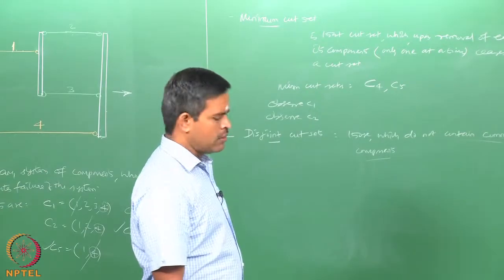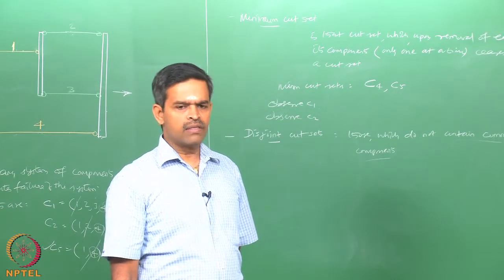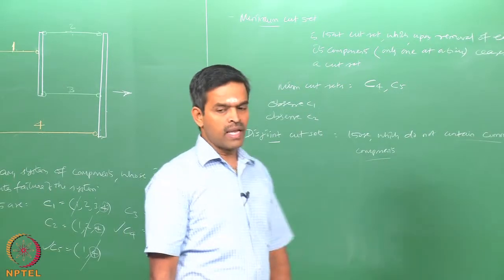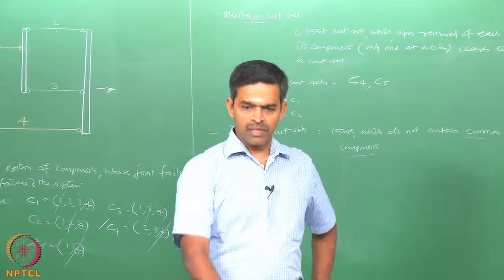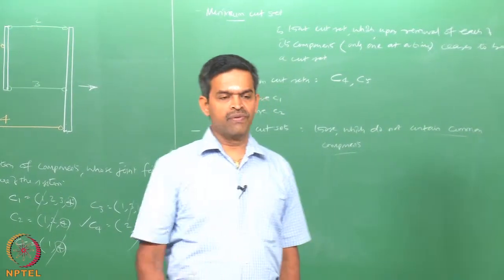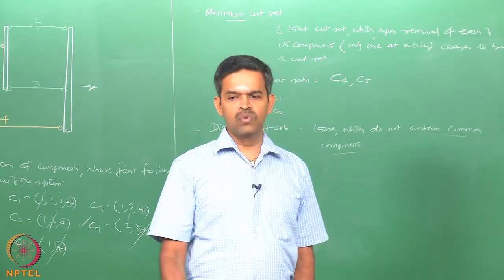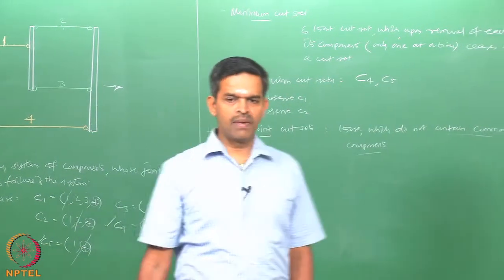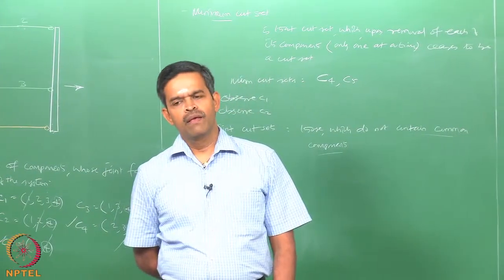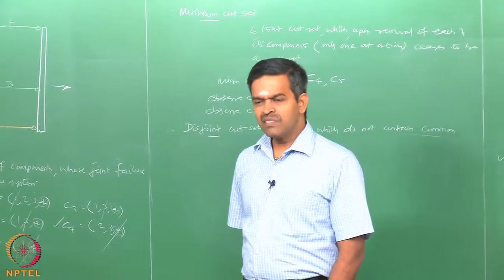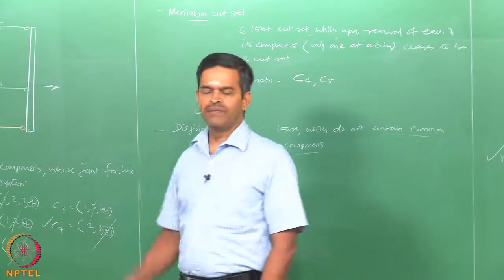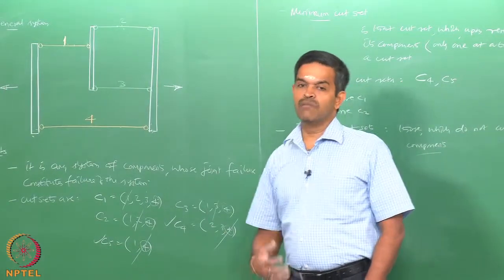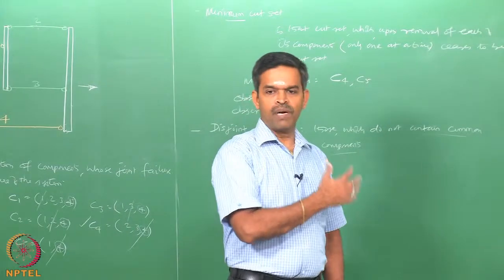So, friends, we are continuing the discussion on system reliability. We are identifying the series and parallel system. We are also identifying the combination of series and parallel system. To understand the analysis of series and parallel system in particular or general system, to be very specific, one should be able to understand the analysis through some definitions like cut sets and path sets for a given general system, which is a combination of series and parallel system as you see in the blackboard here. We have extended the discussion to really understand or list out the cut sets and path sets from a general system. From the identified cut sets and path sets, we identified also the disjoint sets and the minimum sets for both cut sets and path sets as we have now discussed.